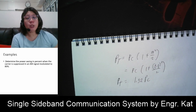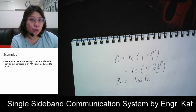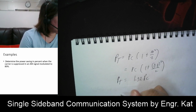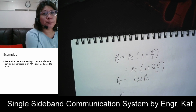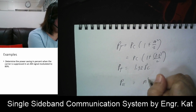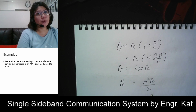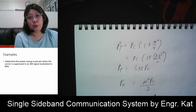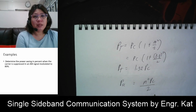If we suppress the carrier, that means we are just transmitting the two sidebands. So our total transmitted power if we suppress the carrier is equivalent to M squared PC divided by 2. Why not divide by 4? Divide by 4 is used if we have also suppressed one of the sidebands. In this case, we are transmitting both of the sidebands and we are just suppressing the carrier.